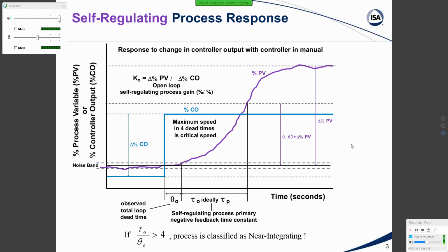It's not going to see the steady state unless you do this open loop test, and for these type processes it's going to take a long time. So there's an advantage, first in terms of the test time, to recognize all I need to do is get this ramp rate, and second of all, I need to realize I should be understanding this process, analyzing this process, and also tuning the controller based on it being a near integrating process.